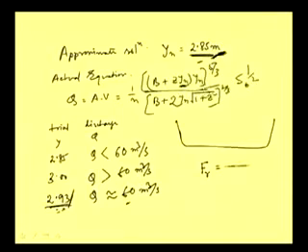That detail I am not going into right now, but we know that the Froude number we calculate is equal to V by root over G D, where D is nothing but A by T. Once we know the depth, we can calculate the D, and V we are already calculating from the Q and the sectional area.